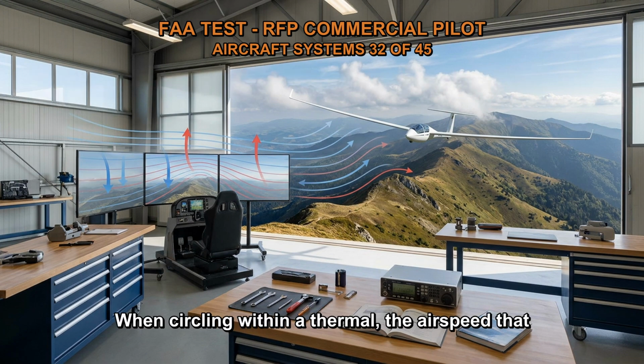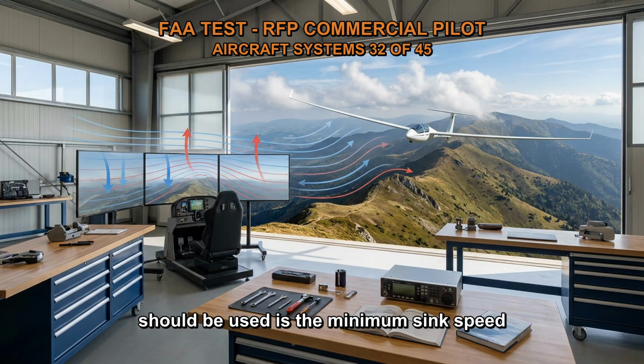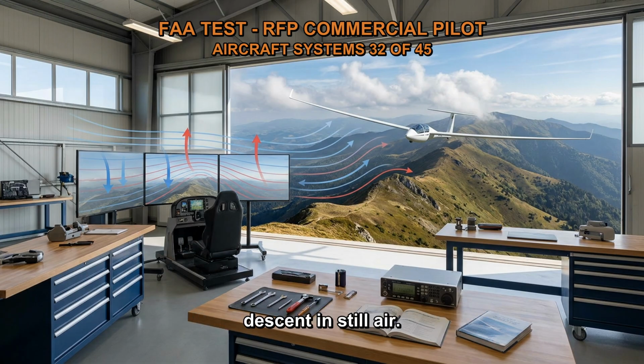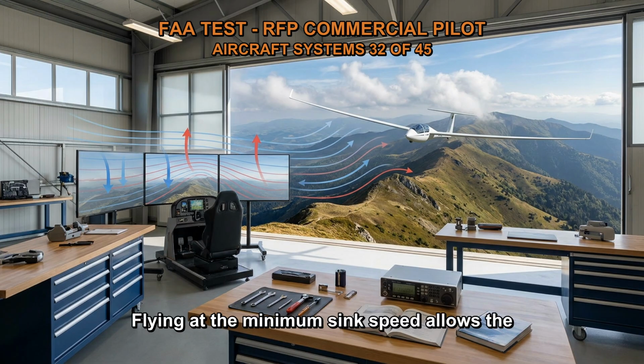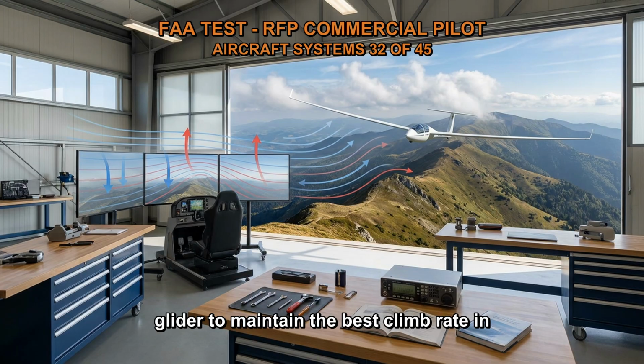When circling within a thermal, the airspeed that should be used is the minimum sink speed appropriate for the angle of bank. The minimum sink speed is the airspeed at which the glider achieves the lowest rate of descent in still air. When circling within a thermal, the goal is to maximize lift and stay within the rising air. Flying at the minimum sink speed allows the glider to maintain the best climb rate in the thermal.